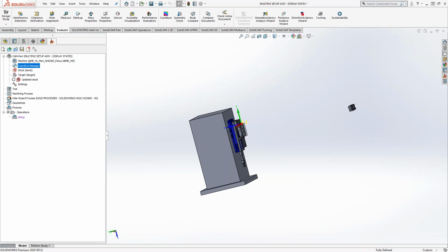So regardless of the shape of that geometry, the diameter of that hole, or the location of that face, those faces, those holes, those edges are being called out by their ID number. So that toolpath is looking for that ID number and then just following that specific path. Whatever toolpath you're using is going to follow the ID tag rather than that specific configuration, or rather the current status of that geometry or that feature.